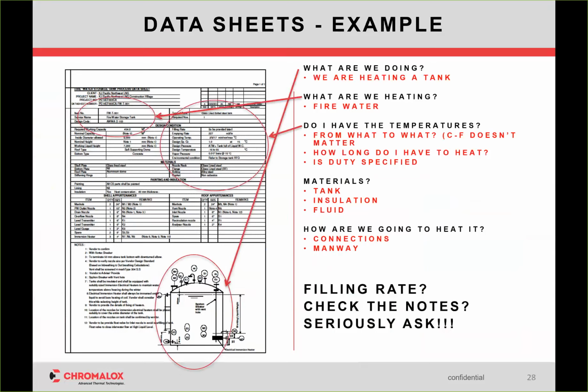So back to the input temperatures. We're heating it from what to what? That's going to give you a starting point, a line in the sand, and then time has a factor in it. Heat loss has a factor in it. Insulation has a factor in that, and that goes through the materials. A polymer tank is actually, a polymer is an insulator. It doesn't have the heat loss that a metal tank would have. And that's the thing to consider.